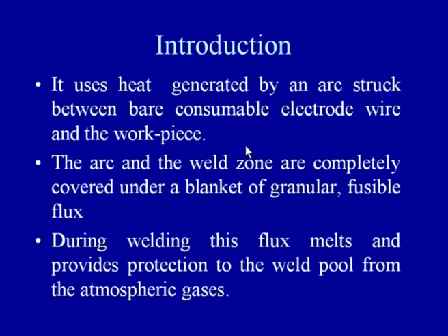So, now we know that in the submerged arc welding process, the arc is completely covered by the granular flux, and this granular flux melts continuously during the welding and forms the complete cover around the arc and the weld pool, to protect the weld pool from contamination by the atmospheric gases. So, during the welding, this flux melts and provides the protection to the weld pool from the atmospheric gases.